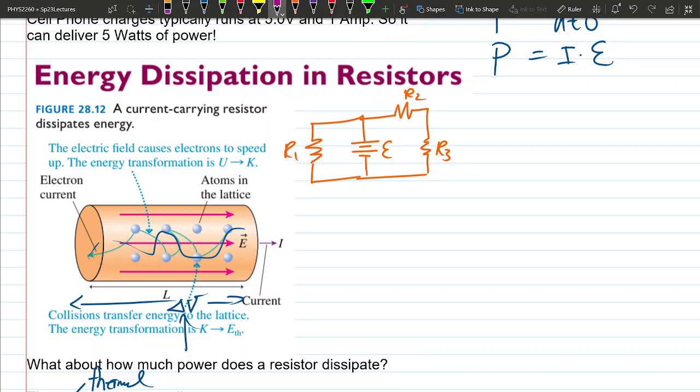Ideally, what you want to do is pick your biggest battery and think that the current is going to flow out of the positive end of that battery, right? So there's going to be some current going to the left, and some current going to the right, but there are two currents, so I better label them, right? And using just Kirchhoff's law, hopefully we can apply it. Let's just do it for the right side.